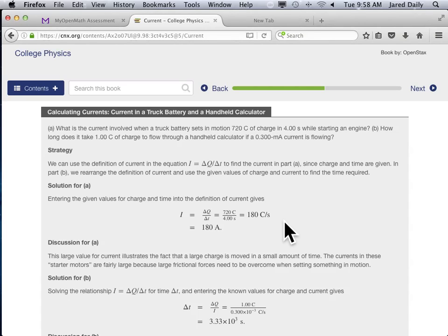Because if you do have enough conductivity in your hands for that 12 volts to break through your skin, because essentially your skin's like a capacitor. Your skin has a dielectric constant to it, has a dielectric strength. And if that dielectric strength is less than 12 volts, because it's wet and your hands are clammy or it's humid outside or something like that, then that current can go through you.